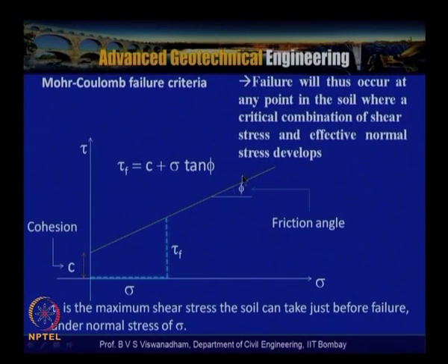When combined with Mohr and Coulomb, this is indicated as a linear relationship within the stress range. Beyond it, at higher stresses, the validity of Mohr-Coulomb cannot be guaranteed; the linearity we assume is valid for the assumed stress range.